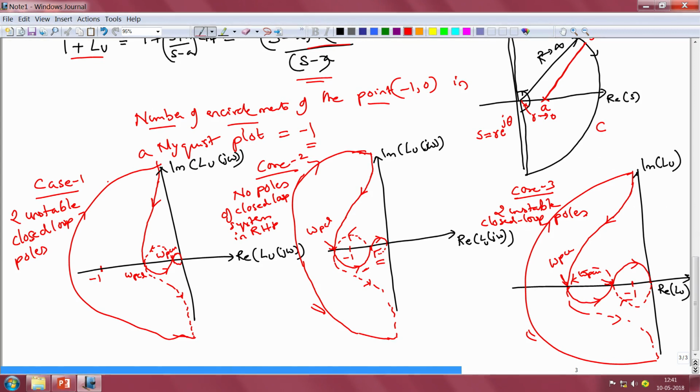So, when the phase characteristics look as unfamiliar and unsettling as what we saw in the previous slide where you had two phase crossover frequencies and so on, the best and indeed the only thing that we need to do is to first come to the Nyquist plot, and depending on the structure of the open loop transfer function, namely whether the open loop transfer function has any unstable poles or not, we first have to come up with the right rules for determining the stability of the closed loop system, and subsequently plot the Nyquist plot for the open loop gain, and then see whether the conditions for stability are satisfied or not.